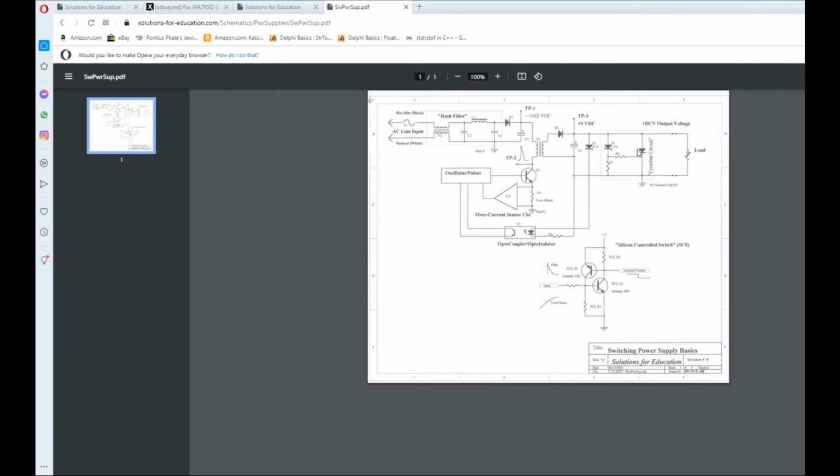So this SCR, a crowbar is what it's called, and it really serves the purpose. It's in there to protect your circuits over here. It is not in here to protect the power supply. It is in here to put a drastic load on this, and this guy here says, whoa, wrong, blow the fuse. That's what it's there for.